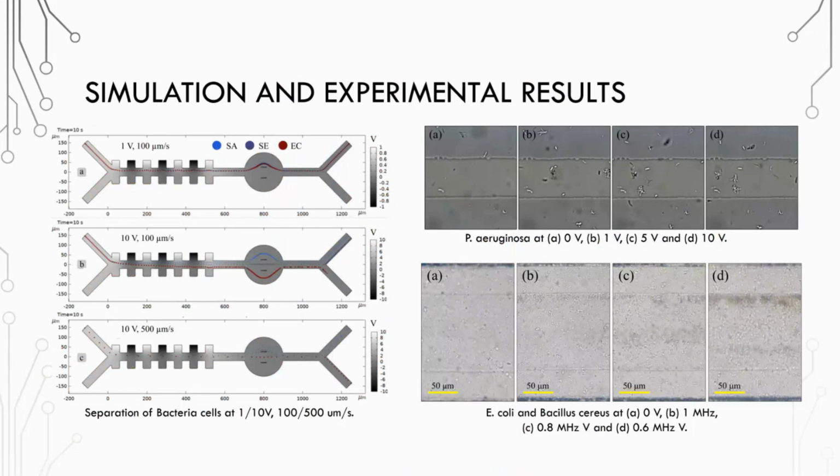So it will happen something like this. I think this is the E. coli because it has a bigger size, so it will repel to here, and only the other bacteria will pass through the electrode. So in this case, if we take the reading, for example, the capacitance of these two electrodes, it will give us the capacitance of only this specific type of cell, while the others we already made sure move away from the sensing electrodes.